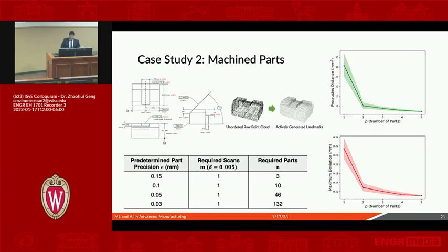Right? Another case study is, again, mimicking the same remanufacturing process. We collected a few parts from the Manufacturing Systems Center at the University of Pittsburgh. We have the original design, so what we do is utilize CMM to measure each part and build the part model to see whether it's closer to the original design. Right? So here we can see that the pattern is the same. With an increasing number of parts, the part model is closer to the original design.